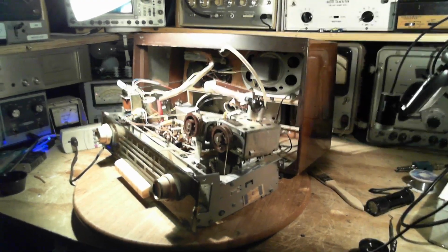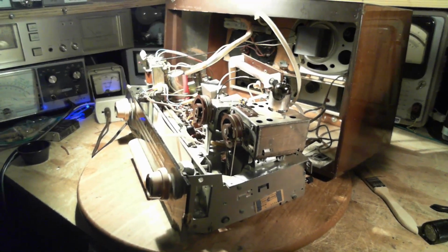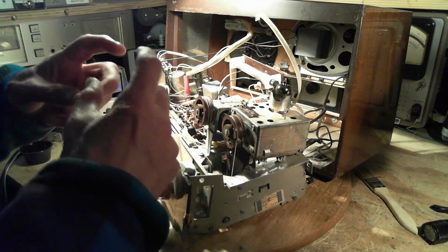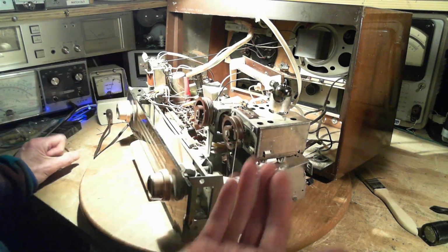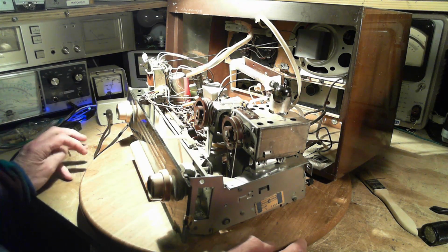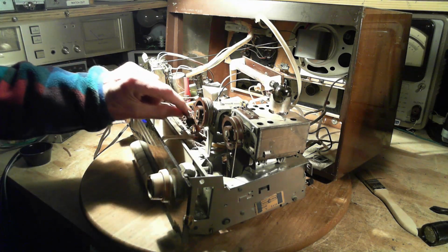Okay, another problem solved, I think. It just seems to have fixed the problem. So I guess maybe my theory was correct. It has to do with the outside foil on the capacitor. These modern yellow capacitors I buy, they don't have the outside foil mark. And I've just taken to kind of ignoring the whole issue. And there's certainly one case there where ignoring it's not a good idea.